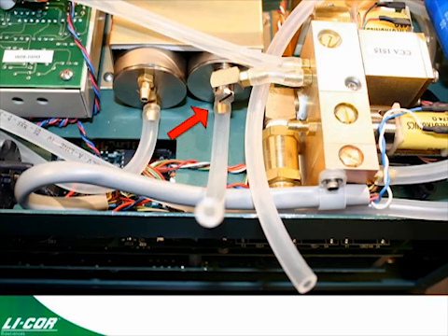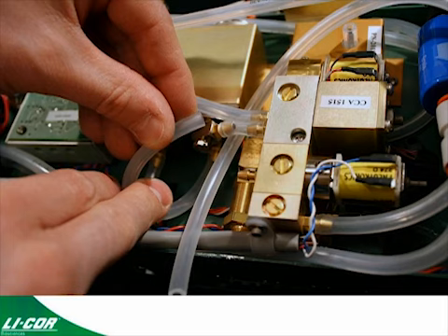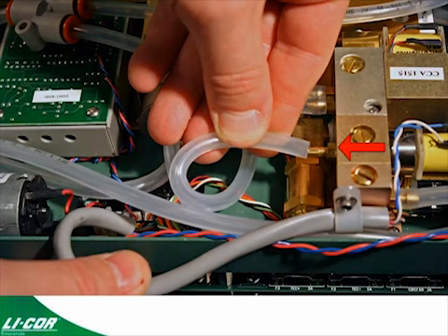Connect the new tube number 4 to the lower barb on the second buffer volume and then gently form it into a clockwise corkscrew. This will prevent the tube from being twisted in such a way that will damage the tube or create a crease that leads to diffusional leaks.